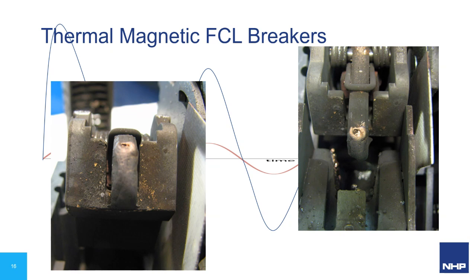Now, a true short circuit event will generally last many cycles, or as long as it takes for the protection device to operate and fully clear the fault. So in the event of a DOL start with IE3, IE4 motors, this high inrush current may manifest itself as a short circuit because of the low impedance circuit. It will disappear as soon as the motor stator has established a magnetic field and the current starts to flow in the rotor. After this point, the rotor will develop torque and begin to rotate following the rotating phases and polar orientation of the energized stator windings. This is how induction squirrel cage motors operate.